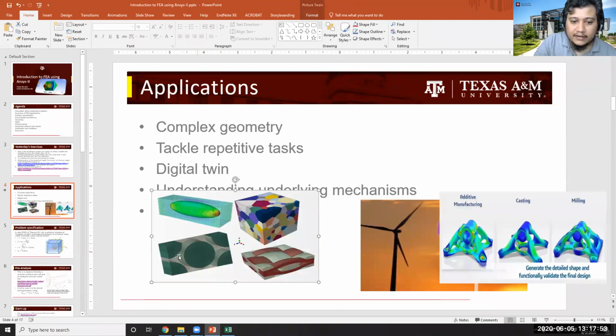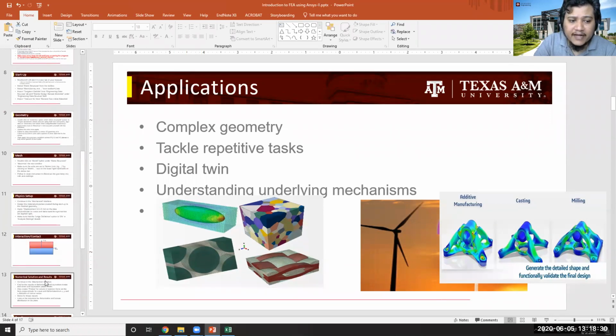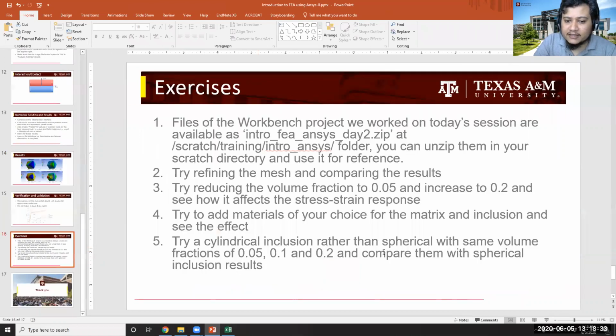this. So it has some fibers at the corners as well. Assume that we don't have any fibers in the corner. Just draw this center part. Okay, so this will give you the practice for fiber reinforced composites part as well. So in that case, you can select the properties of carbon fiber or the carbon nanotube properties. Look for them in the library for the fiber phase, or the glass properties for the fiber phase, and any epoxy properties for the matrix phase. Okay, and play around with different volume fractions.